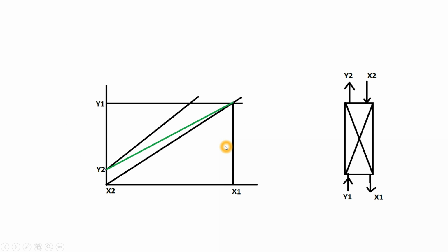Next, you can see here this is the equilibrium line, y is equal to 2x we have given, and y is equal to x is the operating line. Since this is a packed tower, Y1 is entering, Y2 is exiting, that is mole ratio.